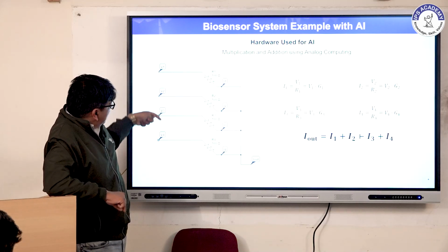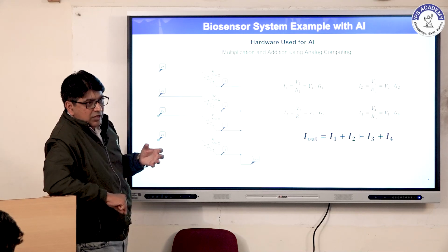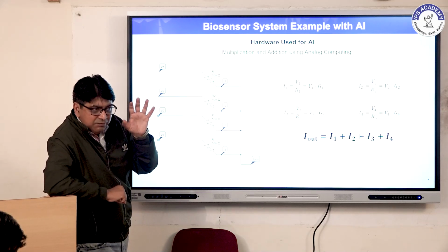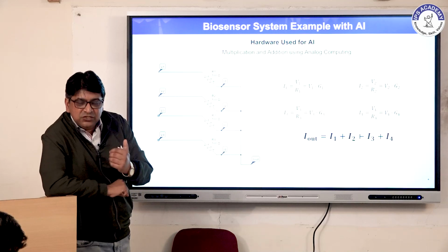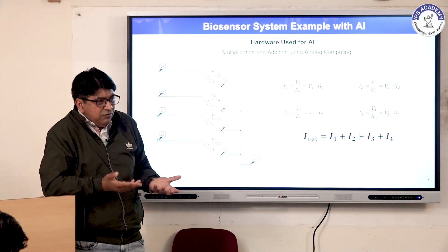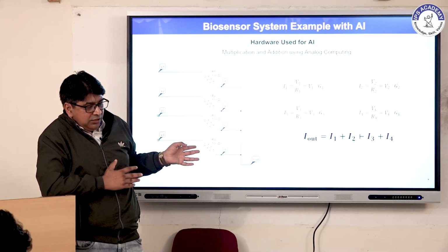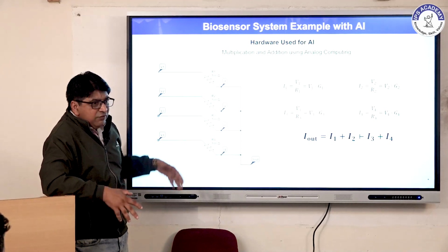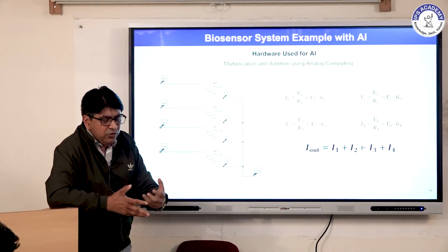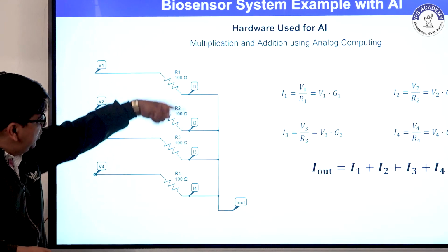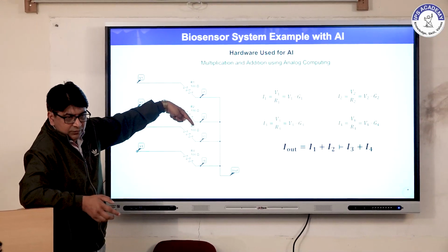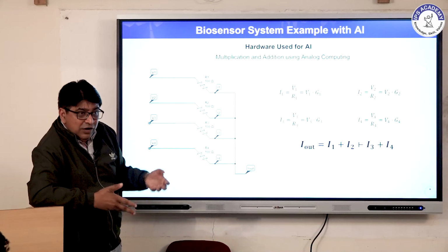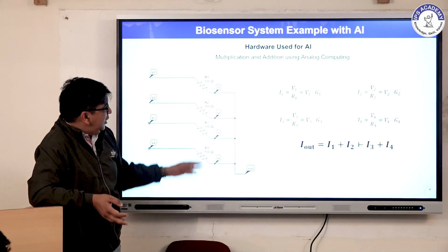That is the analog. These are some voltages that will come. Suppose some image is there. We convert the image into voltage and give it as input. And you have trained one neural network. Once it is trained, it means we fix the weights. Training means weights. Synapses in a neuron are the weights in an artificial neuron. Once you fix the weights, whenever the neural network requires computation, it gets some inputs and sends the information to the specialized hardware, rather than to the digital processor, where multiplication and addition take more time.